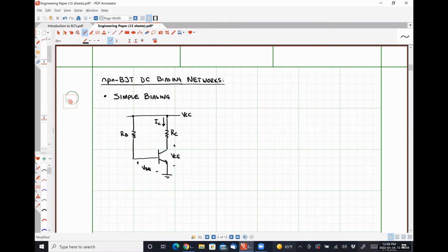So our goal here is literally just to develop an equation or system of equations if necessary that will tell us what our DC operating point for the circuit is, meaning we're just trying to determine the quantities VBE, IC, and VCE, so we can tell in what region this thing is operating and then what those voltages and currents are. Okay.